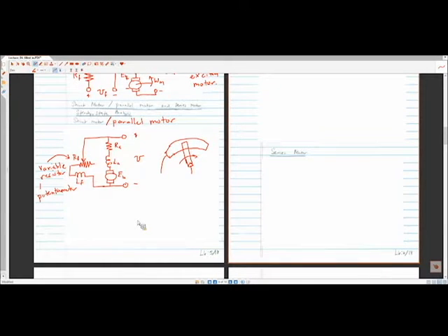Yeah. So it's not changing the number of coils; it's changing the resistance in that circuit, which then changes the current running through the coil. Remember that the flux is basically proportional to N times I. So you're not changing N; you're changing I.